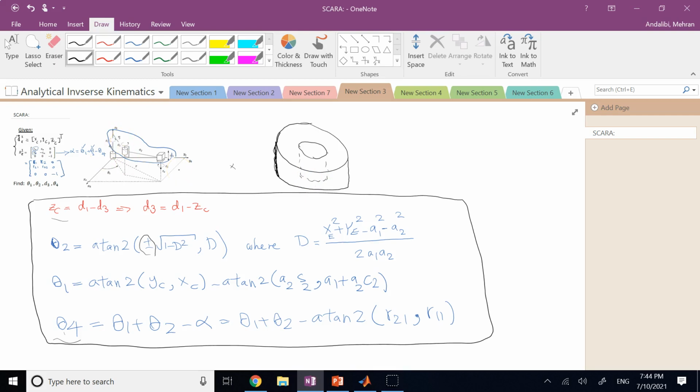Assuming that theta 1 can go full rotation, theta 2 can do full rotation, and let's say this is here as much as D3 can go up and down. Theta 4 is not going to affect anything here in the size and dimension of the workspace. All it can do is whether your end effector is reaching the point like this, or for example like this, or like this, as long as these are all Z rotations. Okay, so it's not exactly like that, so it's like this, or for example this or this.